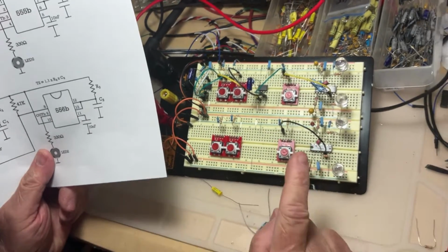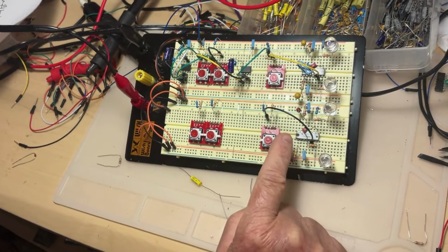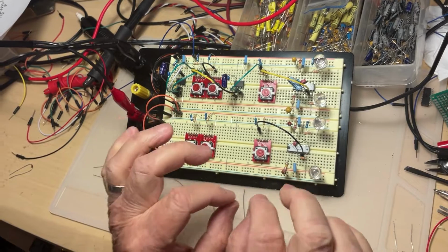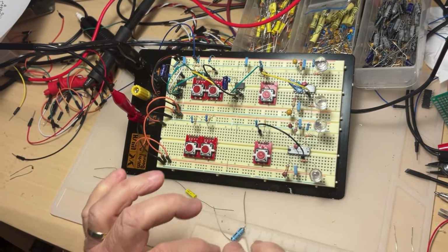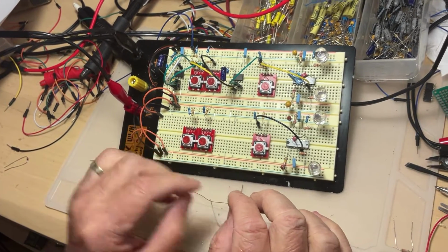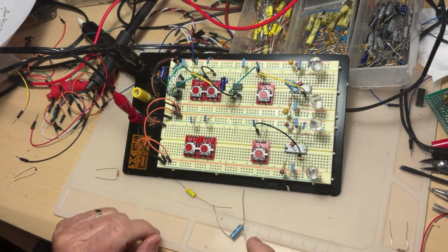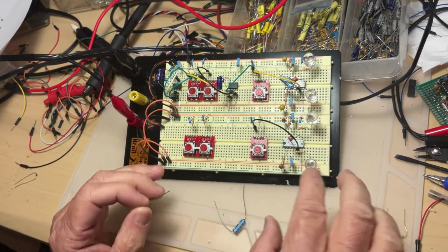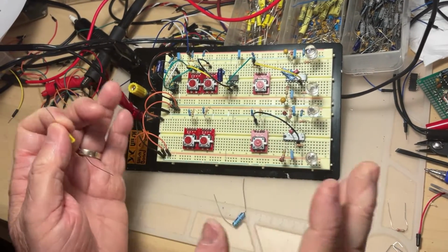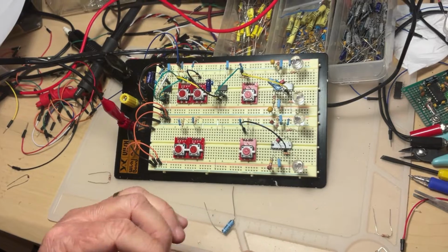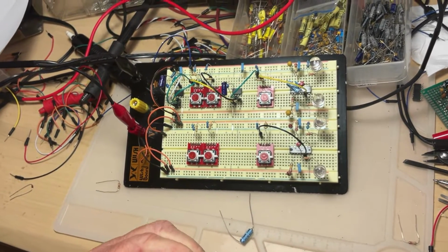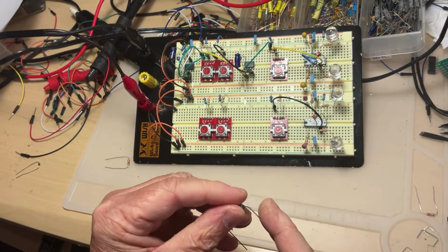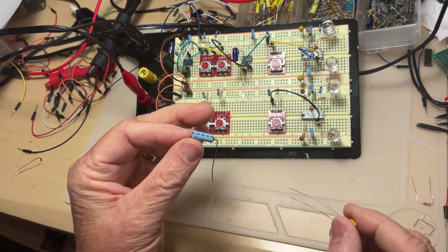So I said there are two things to know about the use of this package. One of them was, don't make connections with power on. The power has to be off. And now I'm telling you the second thing you should do. Any of these two packages, they have a little drawback. They can propagate unwanted pulses if you have more packages to play with, so your project is more complicated. So in order to get rid of these things, you have to connect across the pins of the power supply 1 or 2 capacitors. I'm going to connect 2 just to make sure.